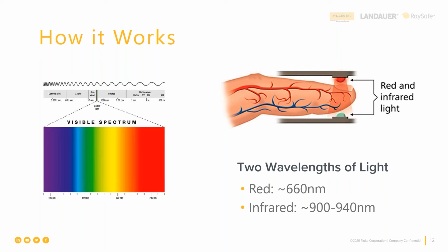That's reflective SpO2. What happens is a detector on the other side of the finger measures how much light has passed through the finger from each type of light. The oximeter only needs one detector that can detect either light because it knows which light is shining at any time. So really, it's what's shown in that image there. We send a signal through one side of the finger, and we receive a signal through the other, and the math behind it, and we'll jump into that, tells you what the oxygenation level of that blood is